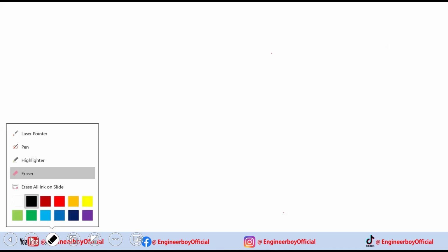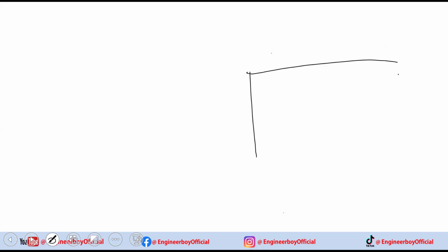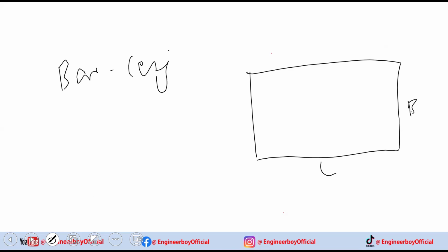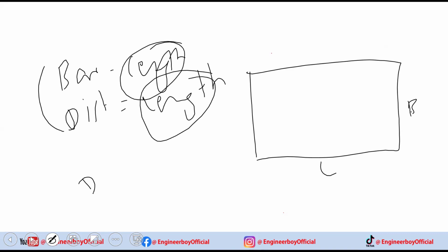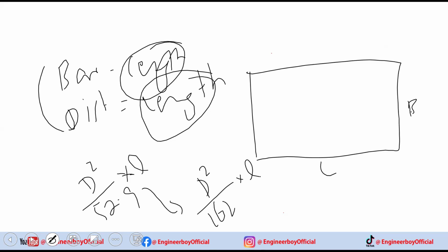Now, it's really important, okay? If you remember, we did the steel calculation for a slab, but that was a manual calculation. Let me just have a pin over here. For a slab, if you remember, we had a slab with length and width, and then there was a thickness. Over there, what we did is we determined the main bar's length, then the distribution or temperature bars' length. And based on the diameter and the length of the bar, we used the formula for the weight calculation, if you remember. So we used two types of formulas for the weight calculation.